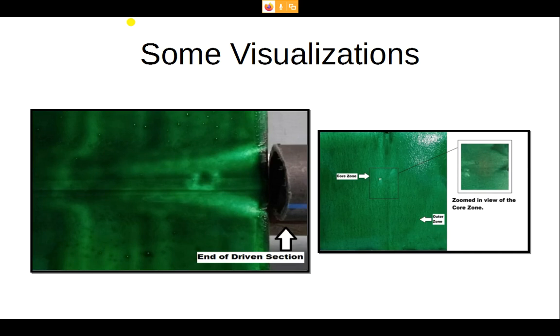Also on the left side, we kept the same plate again freshly painted with the paint and thinner in an appropriate mixing combination such that we can trace the flow. So we kept that at the end of the shock tube and we ruptured the diaphragm to see how the shock moves out of that tube and how it behaves when it interacts with a wall. So this is the trace which we are seeing. We have the highest width near the shock tube end, and as it moves it loses energy or strength, and you might find the width is reducing as you move towards the left side. So this is what you are seeing from the visualizations which we performed.